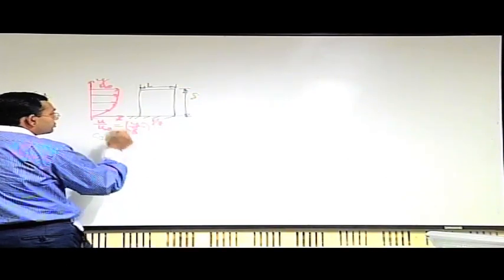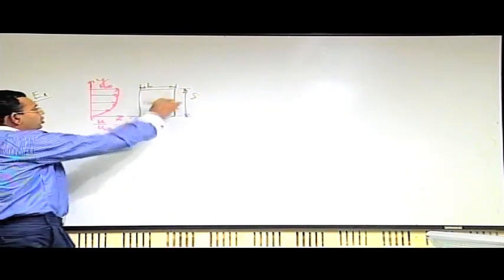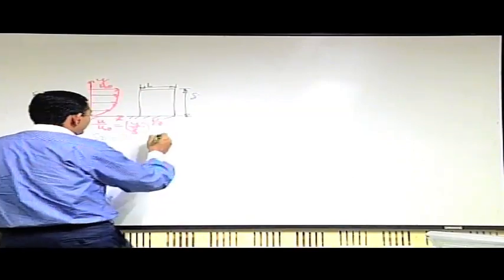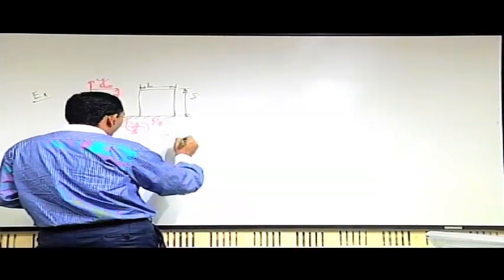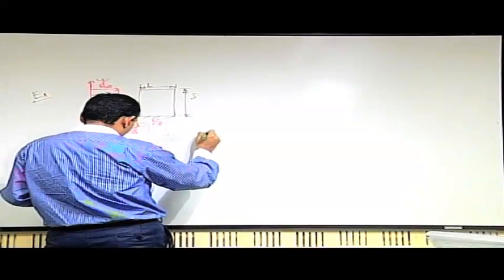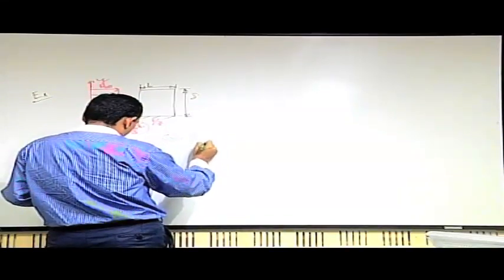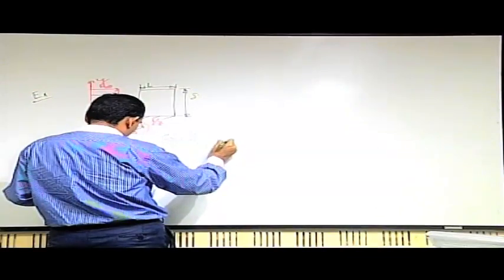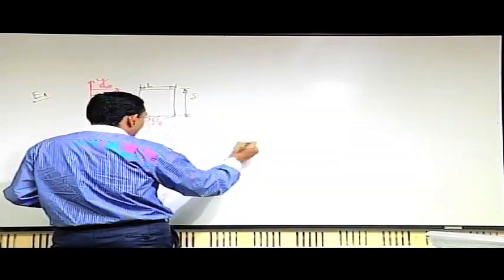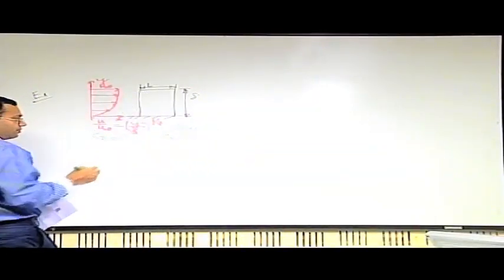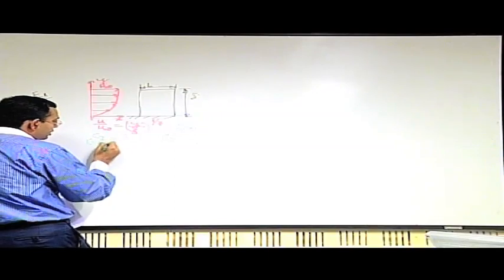You have to find out what is the total drag coefficient or the net drag coefficient because of the interaction between the fluid and the solid plate. What is given is that for a turbulent flow you may assume that the CD is 0.031 by (rho UL by mu) to the power 1 by 7, that is given. This is the CD based on a local velocity, this is the CD net, that is the net effect on the plate. What is the equivalent CD that you have to find out.